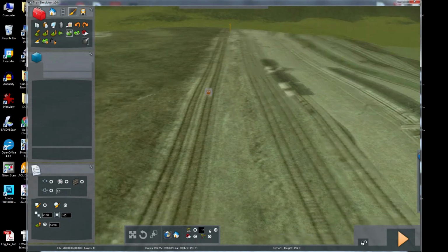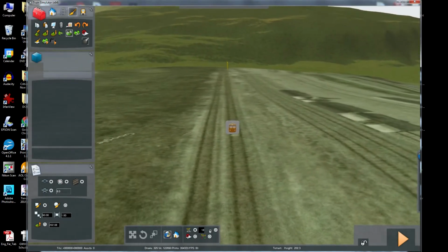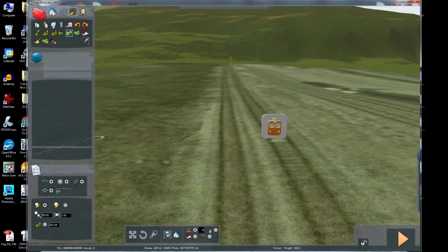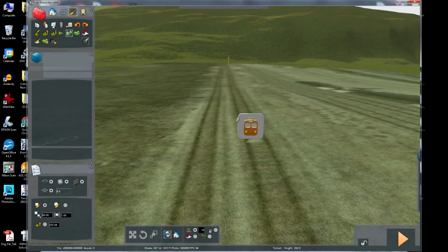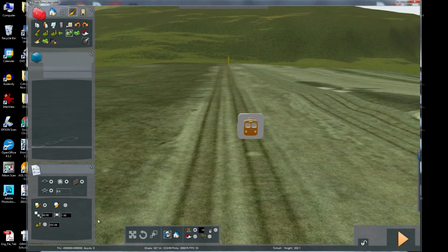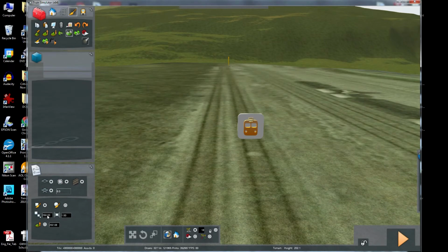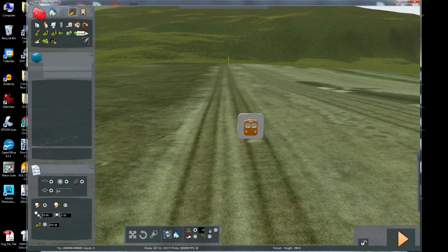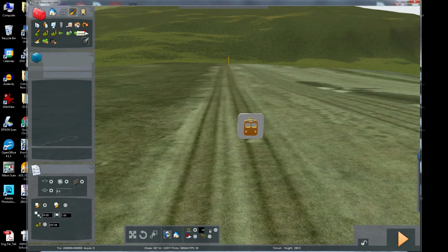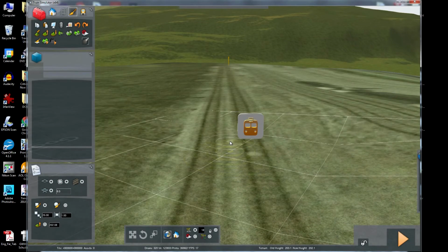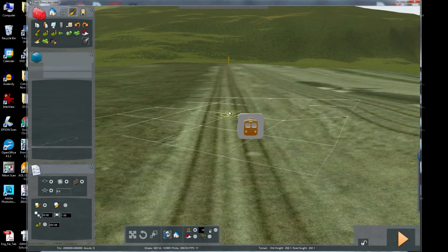Now, when I come over here and I use my brush, I'm going to run over the track area. Oops, I need to change the size of the brush down to about 25. And we're going to set that elevation, not 250, I said 25. Let's click the undo a couple of times there and get us back a little more the way we should be. Alright, so we're going to set the 663.